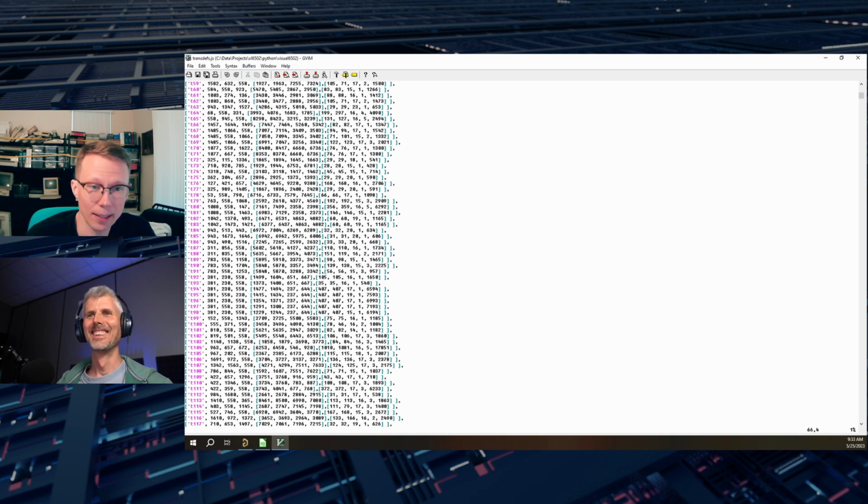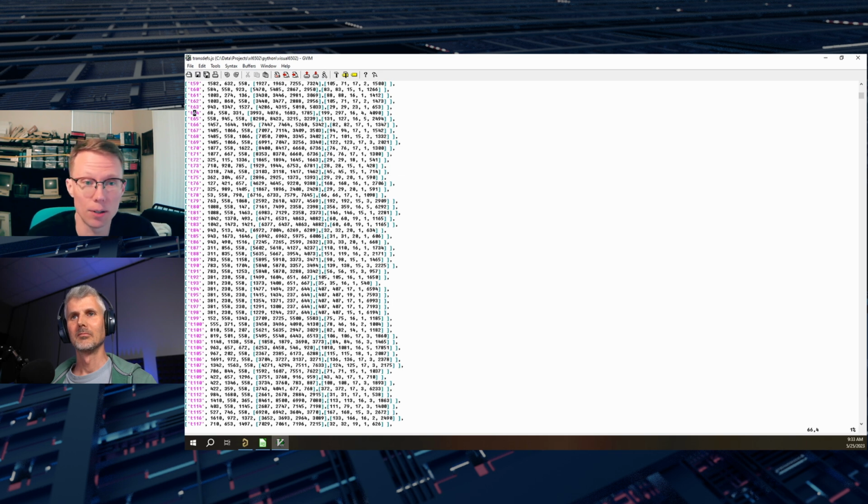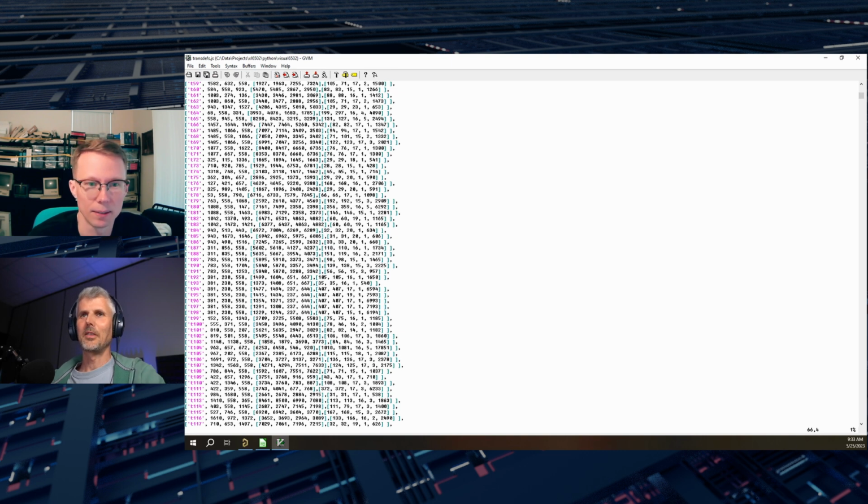Right. I mean, technically, I could have done something like this. I could have written a program to take this JavaScript file and turn it into a netlist that I could have imported into Altium Layout. And I think it would have worked, and it would have saved me maybe 6 months, but it would have cost me a lot later on. It's much easier to troubleshoot a design when you have an actual human readable schematic rather than something like this. Yes. And I've seen the schematics on another interview that you did, and they're very nice just on their own as a way of making it much more understandable.